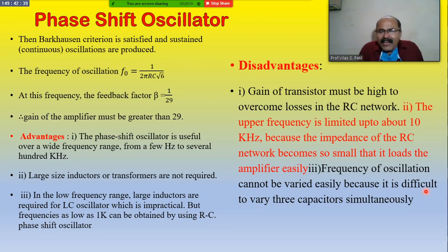We know that in this phase shift oscillator, the tank circuit is not used. In a tank circuit, the inductance and capacitors are fixed in parallel, and we know that inductance is a bulky component. Also, it is expensive, and the electrolytic capacitor is also a bulky component.